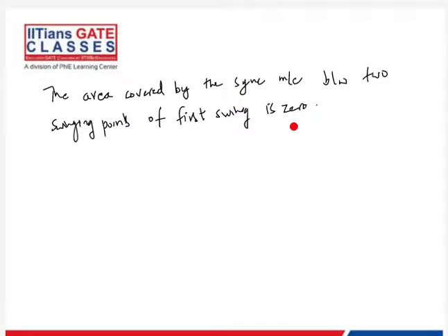So basically, they're saying that suppose a machine starts oscillating due to transient stability analysis. So the first point and the second point, if it swings between these 2 points, between the final steady state point, this area and this area will be the same, right? So basically what happens when the fault or any situation happens, there will be an acceleration or a deacceleration, which will cause the machine to go from the current point to this new point, right?